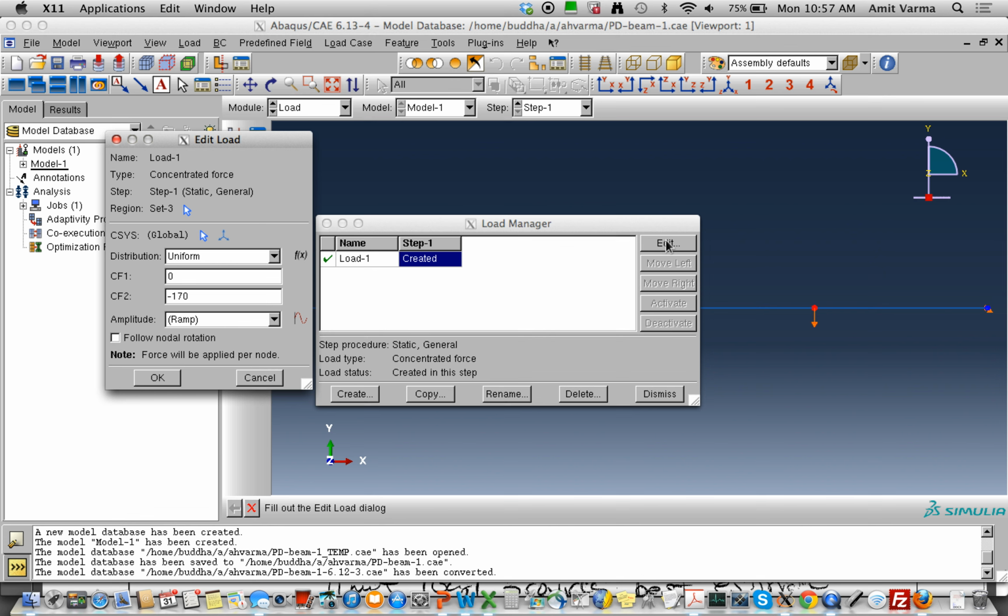Of course, if your load displacement curve is doing this, even the Riks method will have a hard time finding a solution because it will have a very hard time finding a location point that's right there. In that case, you'll have to switch over the analysis method to explicit analysis, because that will probably be the only one that can find a solution for you. But in any case, we are doing it in load control, force control. You can do it in displacement control. I'm not going to stop you.